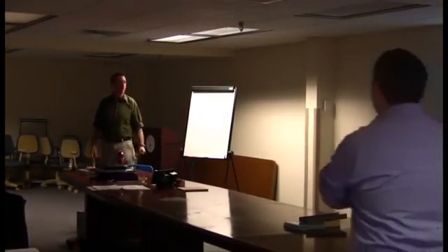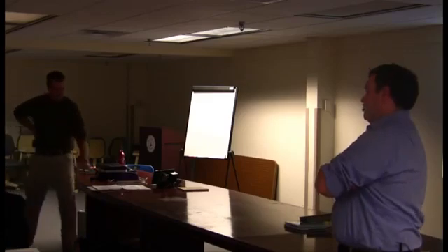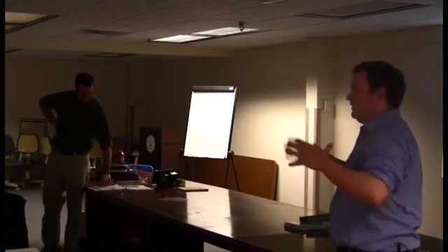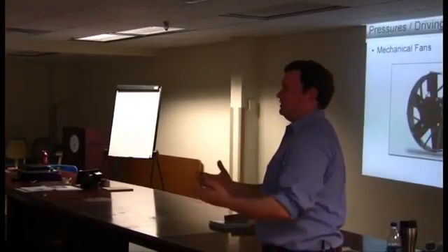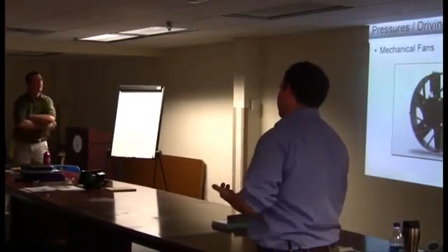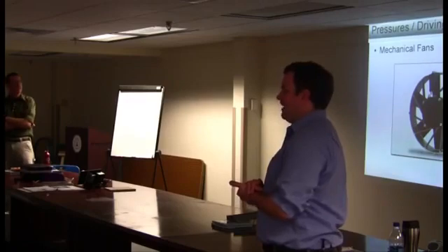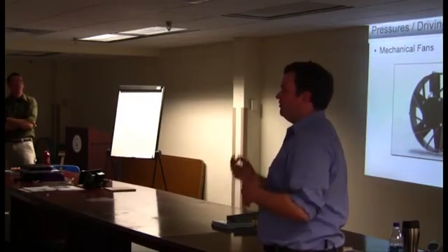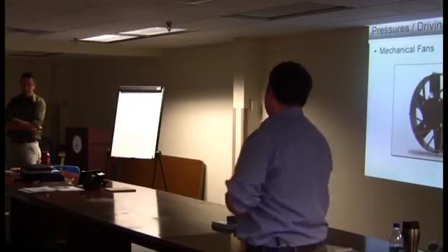And then the last section is mechanical fans. We kind of alluded to this. Obviously, the bigger the building gets, the bigger the mechanical systems get, the bigger the fans are. And whenever we're moving air around a building, you have basically the opportunity to create positive and negative pressure differences within the building itself. And also going back to the idea of whenever we exhaust air out of a building, the same amount of air wants to come into the building. So the bigger the mechanical fans get, the more you really need to plan to basically have balanced pressurization. The same amount of air being made up is being exhausted out of the building.